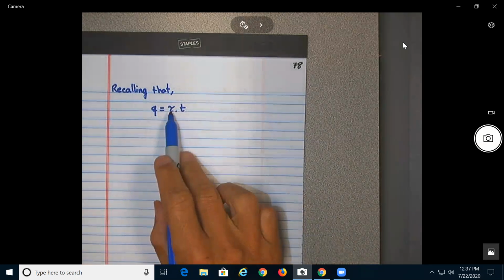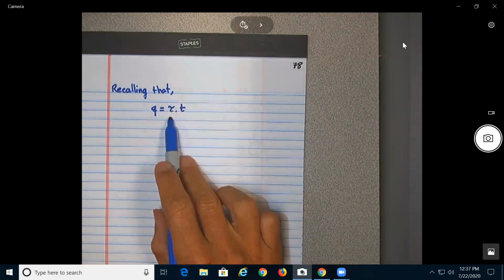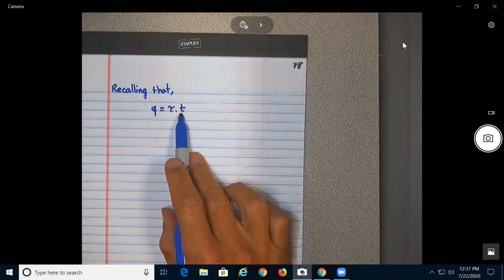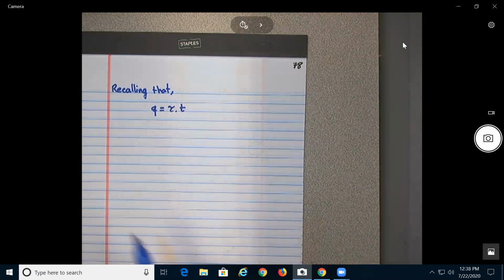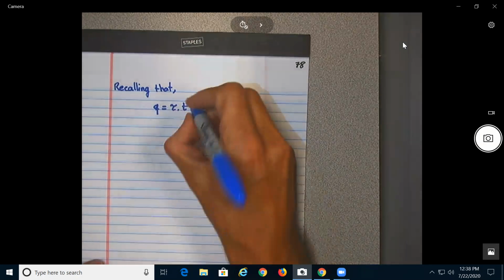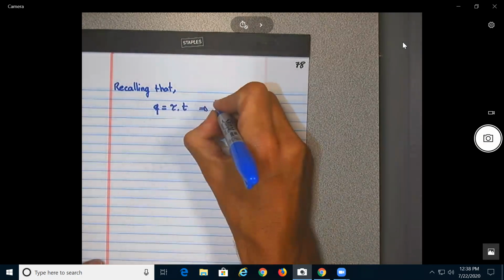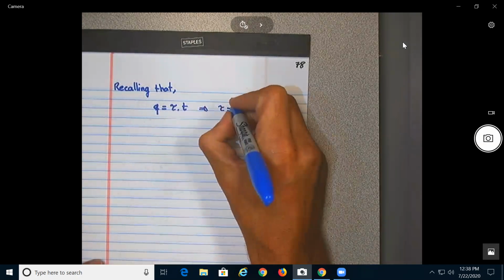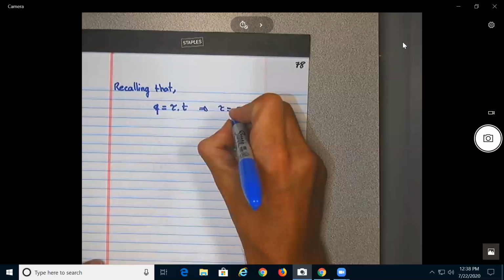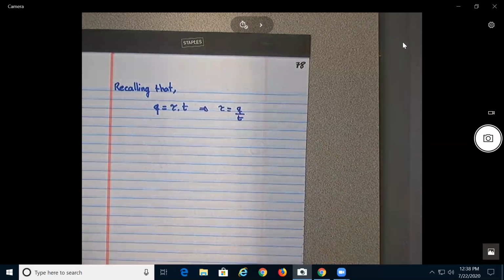So if this will be force per meter squared, newtons per meter squared, if you multiply by meters, you will have newtons per meter. So this one will just tell you then that the tau, the shear stress, is equal to the shear flow divided by the thickness.